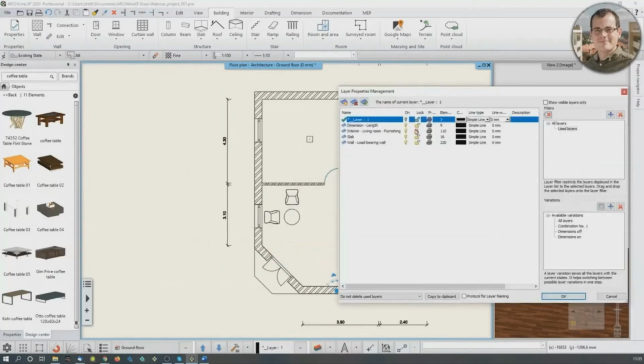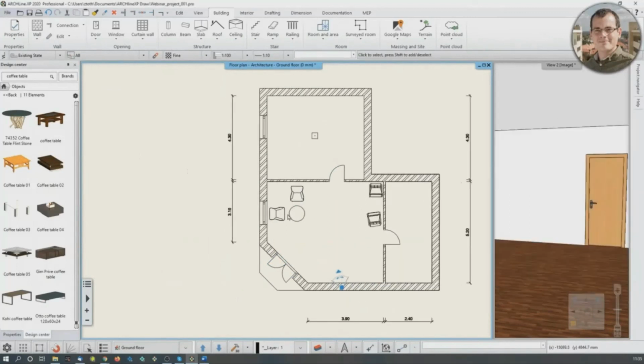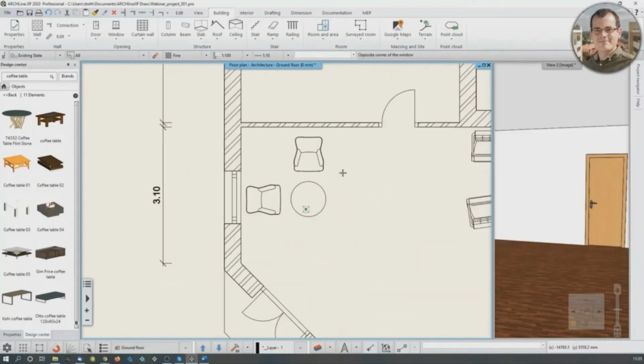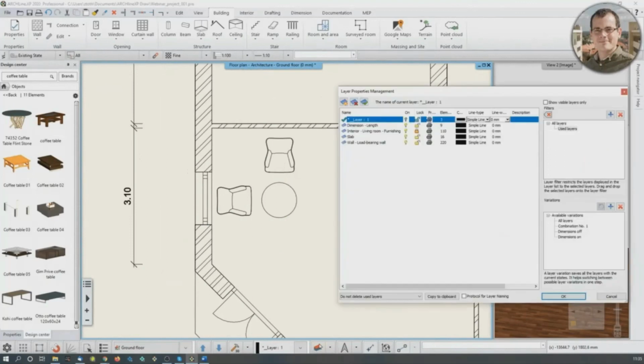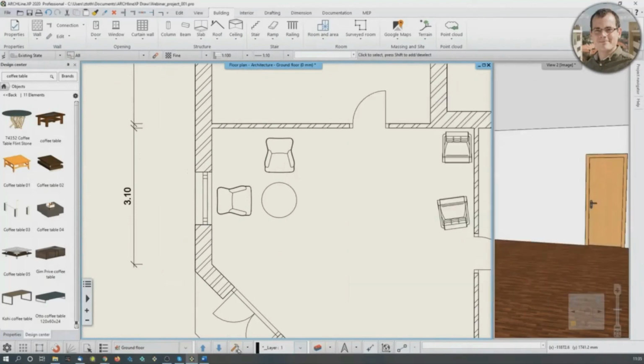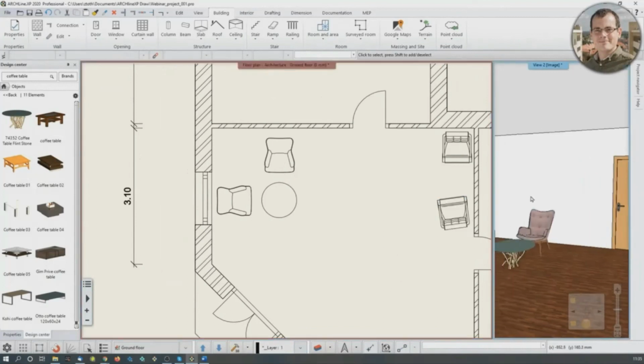See, this is something I also wanted to show you, but I wanted to do it at a later stage. Every layer has 2 settings. One is the visibility and the other one is the editability. This padlock shows you what are the things that you can edit. So if you have the elements like this, then they are going to be shown, but you can't access them anyhow. So you just have to go back to the layer manager and turn on the visibility of these layers, and then you will be scot-free. Now, see, the elements are back.